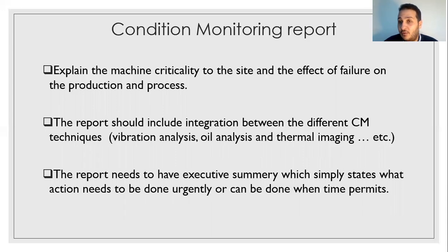And even if you have, for example, machines which need integration between these techniques, like a gearbox, this is a very good example. When you have a big gearbox, you collect vibration analysis data and oil analysis as well. And in this condition, especially for the gearbox, oil analysis is a very essential tool to make a decision about the machine condition.